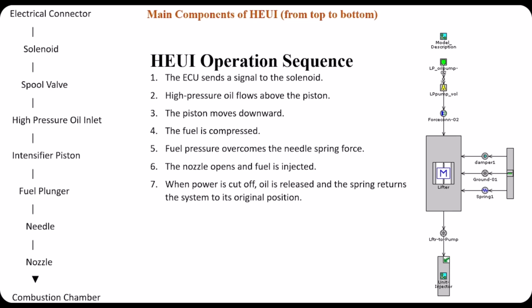And the system contains an environment object. You can see in the picture. To model a constant low pressure source supplying fuel to the injector. The fuel from the low pressure supply flows out to pipe, representing the lumped effects of the entire low pressure system.